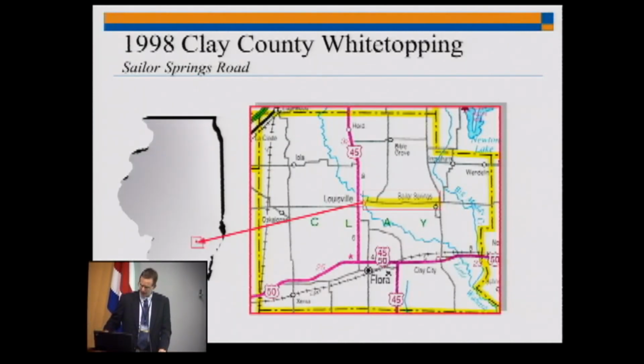But you can have unbonded overlays on asphalt also. So you could have a very poor asphalt with a lot of cracks, and you just are not going to assume there's a bond there. Okay, so that would be considered an unbonded overlay, quote, a white topping, but you have to make the assumption that there's no bond there.